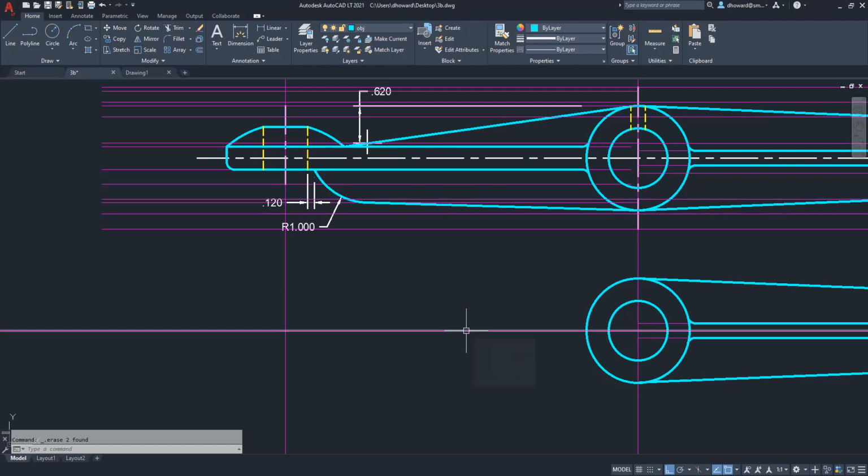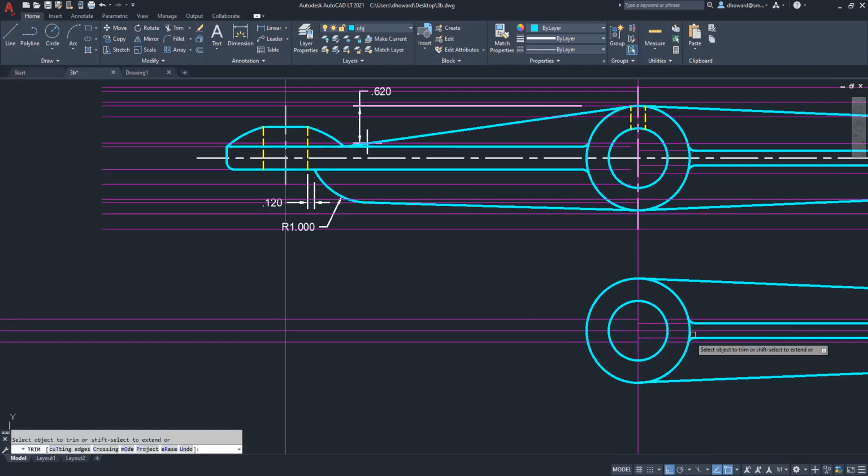And offset this center line the thickness of the webbing in question. So the webbing on this side is thicker than the webbing on this side. This side it was a 1/4 inch total. On this side it's 0.38 total. So my offset is 0.19 up and then down, 0.19 up and then down. And so that will give us this thickness in the middle.